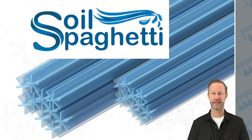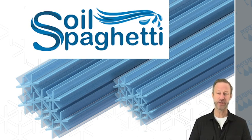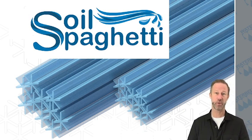Soil spaghetti. Let's talk about soil spaghetti, the most recent technological innovation for draining groundwater. Soil spaghetti also collects water directly from the soil by capillary and has all of the advantages enjoyed by Waterbelt. The differences are in the mechanism for collection and the preparation and installation methods. While Waterbelt collects water into a small internal cavity, soil spaghetti uses specially shaped rods which then combine together, create an expandable network of channels which collect and transport water.